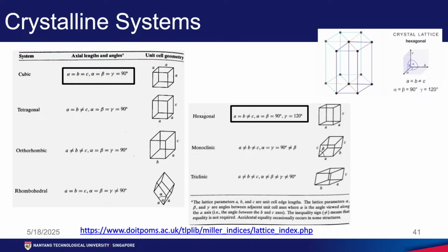So, tetragonal system is very similar to cubic, only thing is you stretch a bit. Okay. The C is longer than A and B. All the other things are same. So, it is like if you place 2 cubes one on top of another, you can say it is a tetragonal, because the C is now 2 times A. So, A is equal to B, but not equal to C is the definition for tetragonal. Orthorhombic, A, B, C all are different. Okay. The lengths are all different, but the angles are all 90 degree. So, like that you can do various types.